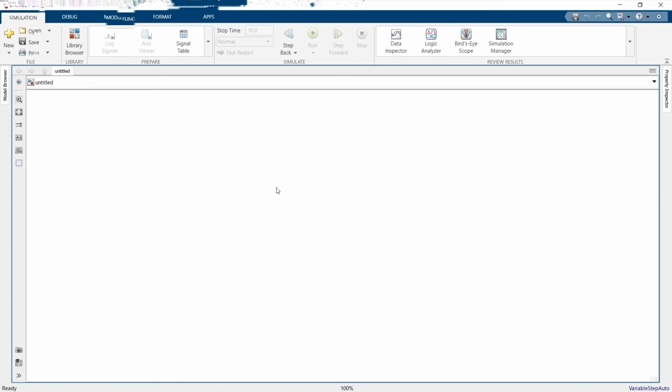Then I'll call a constant block for the output from my port 3. I'll go for 0, that is the off signal. That means if none of them is providing any signal, or if there is no signal from my charger, then this zero signal will be provided, that is the off signal, meaning the charger is switched off. I'll delete this one and I'll use another output. This output will be my net duty. Now my controller is done.